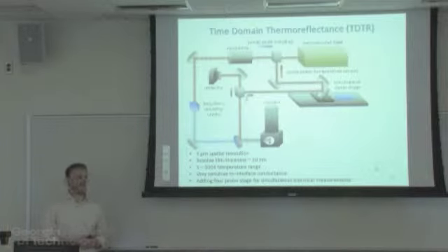This is my experimental setup, but it's also kind of a result slide, because a lot of the work I've done in the last year is setting up this pump probe system. So this is called time domain thermal reflectance. There are quite a few of them around now, but it's a very accurate way to measure thermal conductivity of thin films and interface conductance. So what we do is we take a Ti-sapphire femtosecond laser and we split each pulse into a heating pulse and a probe pulse to sense temperature.